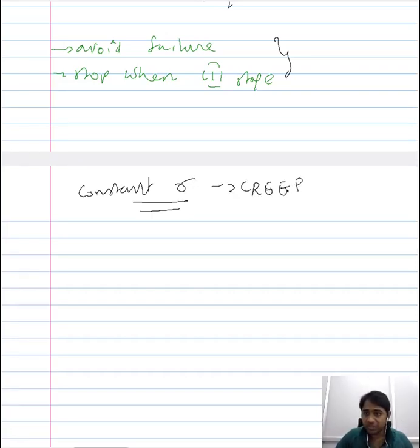And since this constant stress changes with all the geometrical change behavior that is exhibited by the material, like necking, the constant stress that we have applied changes, it means that the deformation till the material fails is unnecessarily prolonged when you use the creep testing setup to understand the failure of the material. So therefore, a different approach is adopted within the framework of creep testing in order to study the failure of the material at high temperature.